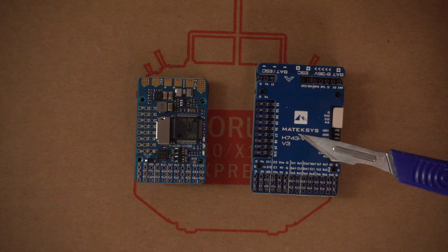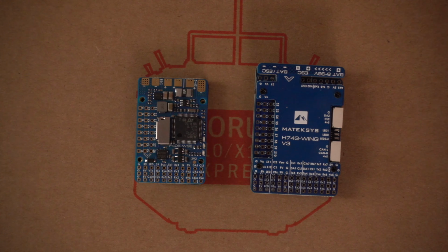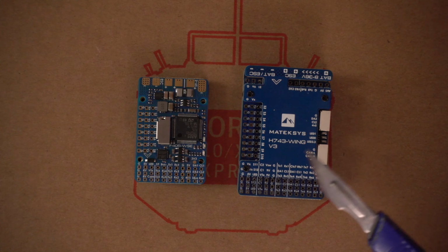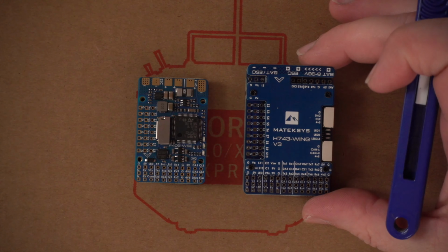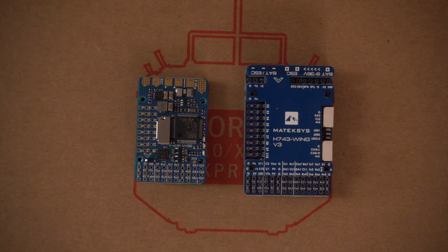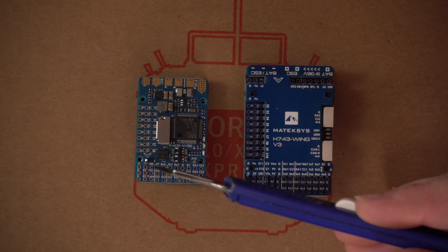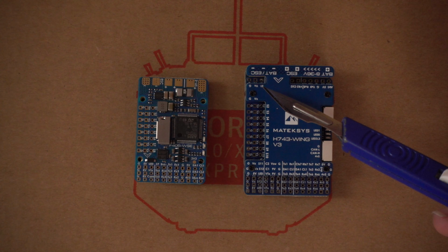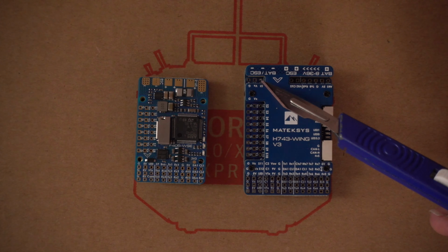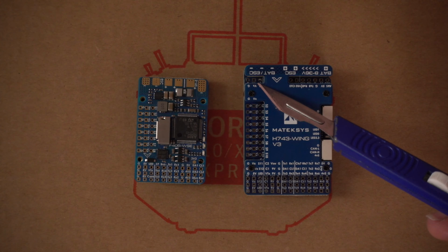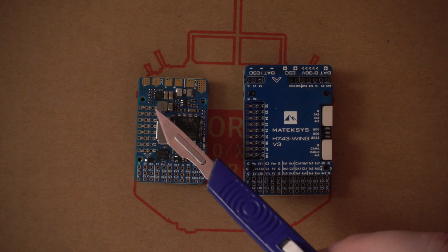With this flight controller, we can actually bridge and raise the VX to 7.2 volts, but most of the 9-gram servos that we get will not handle that voltage. You'll need to get special high volt servos to take that power. So this is where we connect our servos to, the same here. At the back here we have S1, again the voltage at the VX and ground. This is where we would usually connect our motor to. On this one it will be S1.